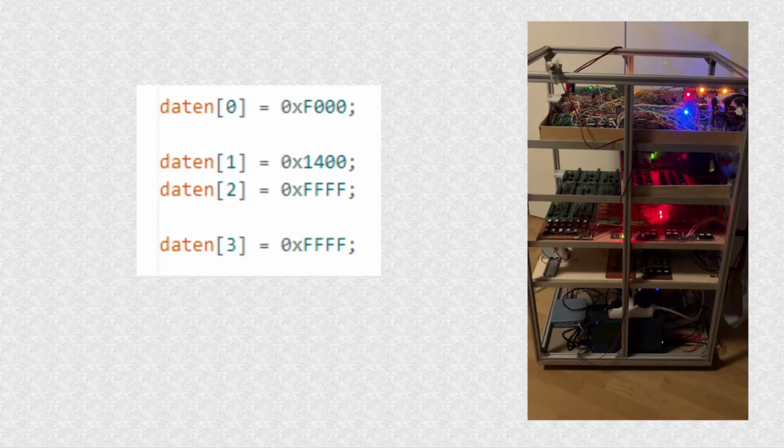So I played my last card and I programmed this program here into the relay system. A no operation command, then load FFFF into the accumulator and load FFFF into the instruction register, which would be an illegal opcode, and the system will stop immediately. But with this little program, I wanted to check if the memory is working properly, or if there is a problem with the accumulator register or with the instruction register.